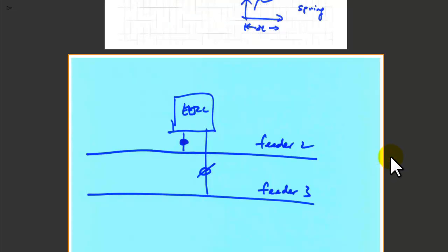So this feeder maximum demand will also be useful to find out the maximum and average value, as I mentioned earlier, which is sort of the way we can derive the loss factor for each feeder. So these are the methods to allocate loads that utility crews have been using to find the best way to model each individual load for each feeder.